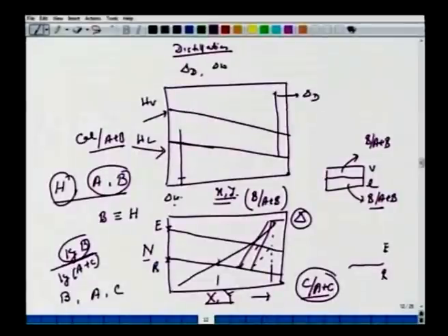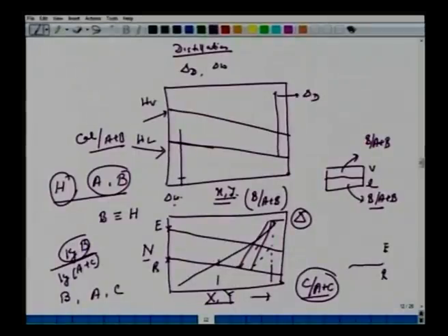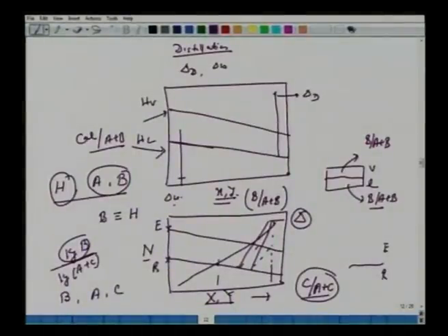Mind you, every stage in extraction consists of two small units: one is a mixer and one is a settler. So to have a cascade of such units, where you have a mixer and a settler, and then you want to separate the solvent at the end and send back your solvent-free solute to this cascade of stages, industrially it's very difficult to do this, to maintain this purity here.